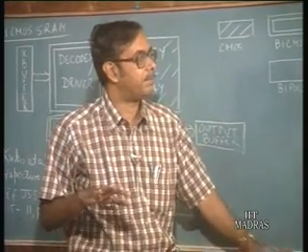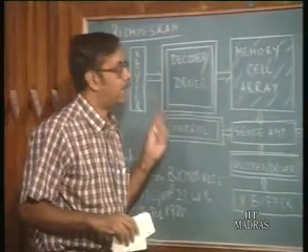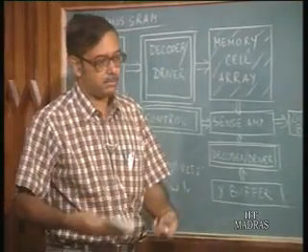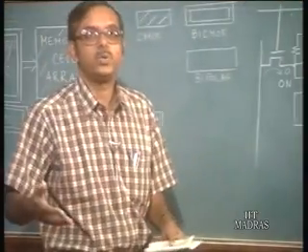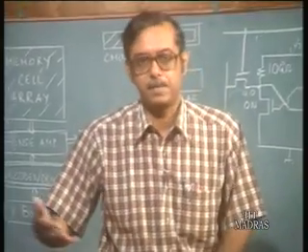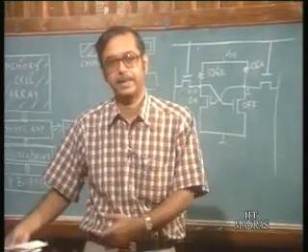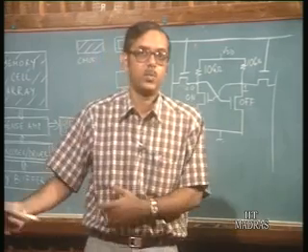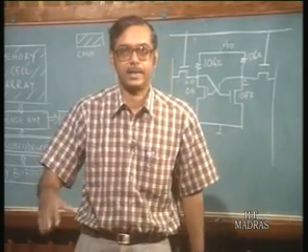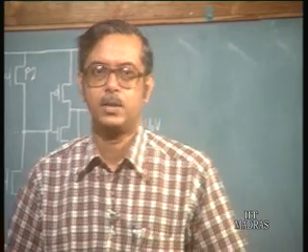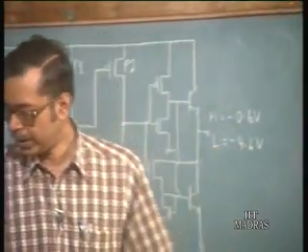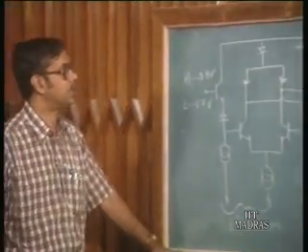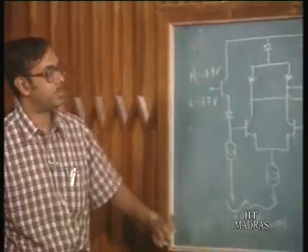We shall now take up the decoder driver part, and see what the changes are, what the circuitry is which is used in BiCMOS static RAMs, basically the modifications with respect to a CMOS static RAM. So, now let us look at the circuits used in BiCMOS static RAMs, the input side.